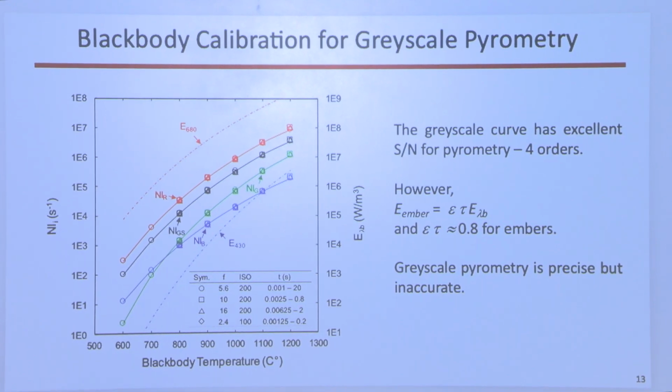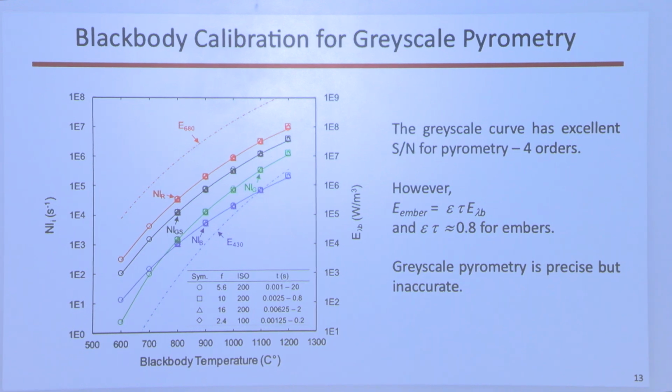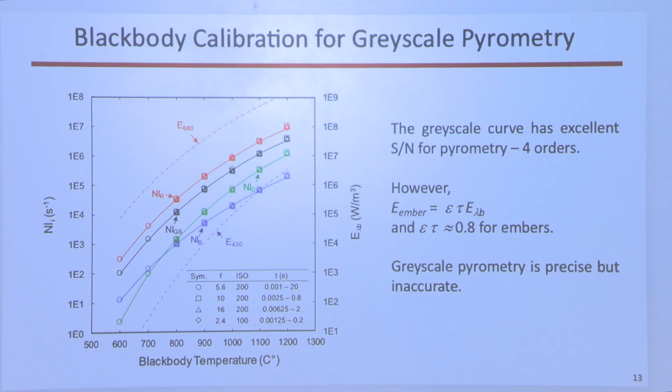Now, thermal imagers can't do ratio pyrometry. They're lucky they can just respond to all the infrared light. So you can't do ratio pyrometry with a thermal imager. But you can with this camera, and you can do it with the native built-in Bayer filter mask.